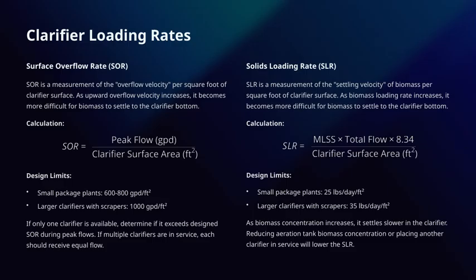This is essentially a measurement of the overflow velocity per square foot of the clarifier surface. Think of it as how fast the water is flowing over the surface. When this velocity gets higher, it becomes tougher for the biomass to settle down to the bottom of the clarifier.